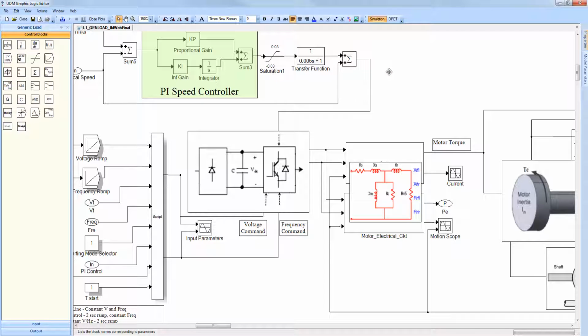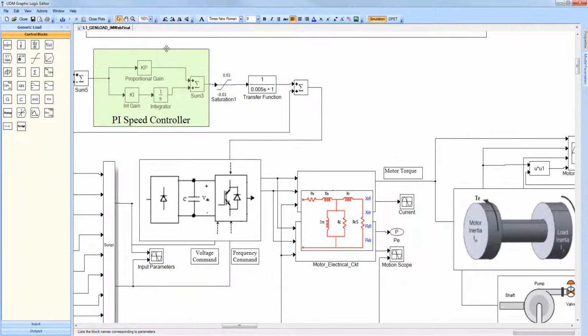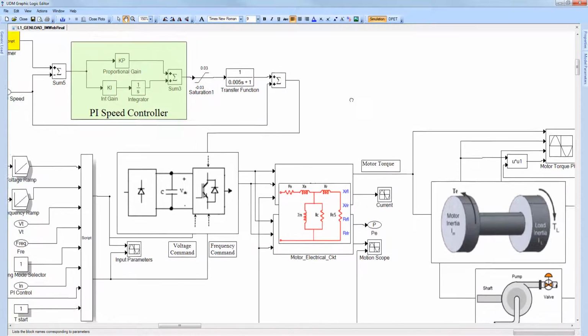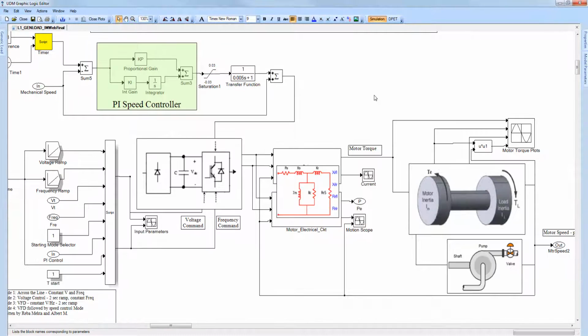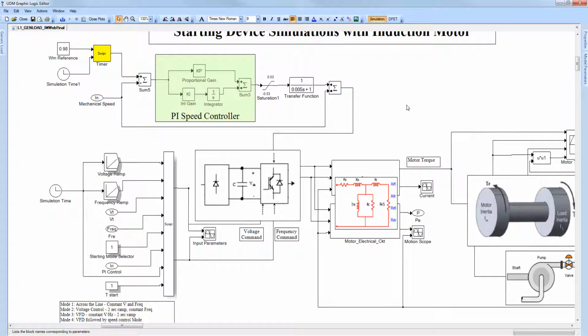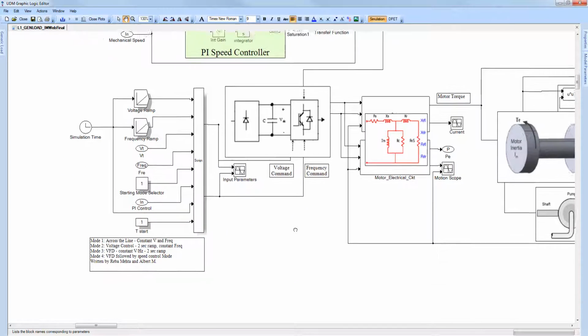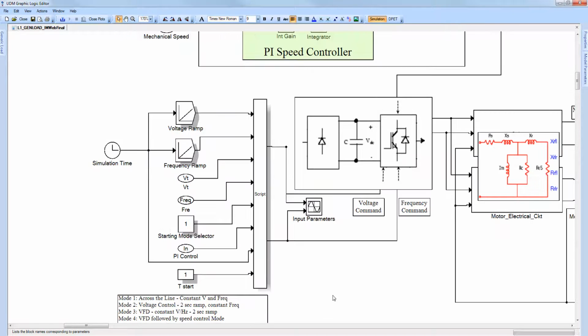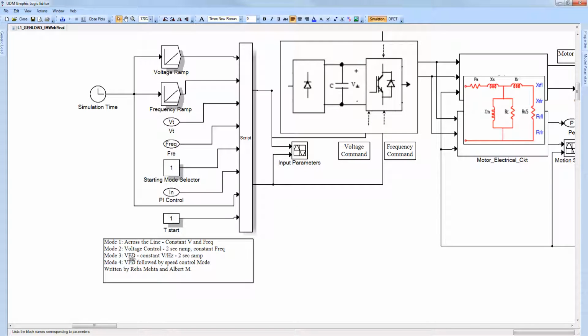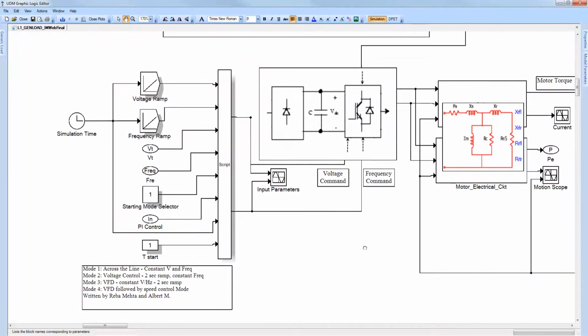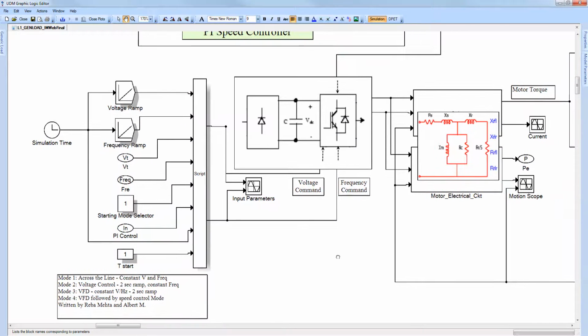Now we can remove our newly created element and go back to the predetermined example that we have on the screen. This particular drive has been configured to allow for a bypass, which will then operate the drive as a starting across the line element. The drive has also been configured to perform a variable frequency drive motor start operation, followed by a frequency control, which will then take the speed of the motor to different operating set points.